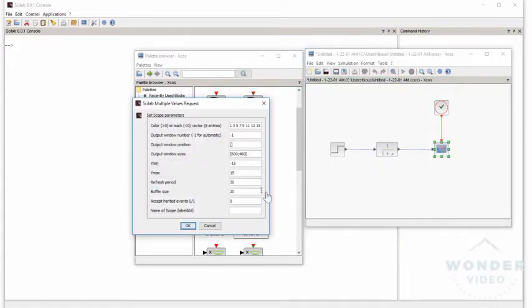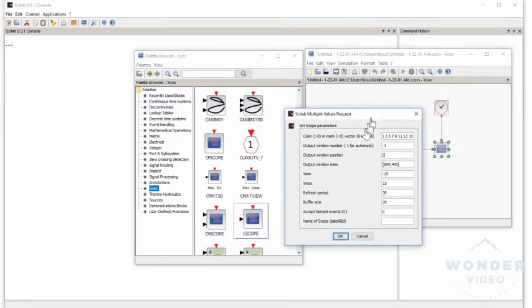In this we also have y minimum and y maximum. Because we are using the step function, and the step function gives 1, we need a value a little bit larger than 1. So we can say 1.2, and y minimum should be 0, and the refresh period should be, you can say 2 seconds, or maybe a larger period, 20 seconds.